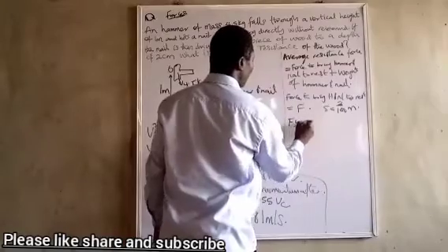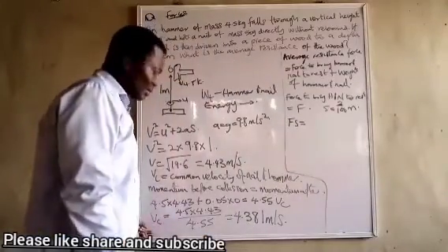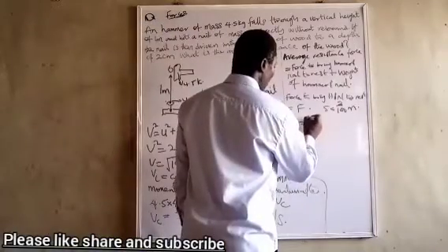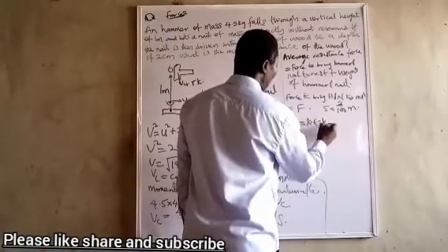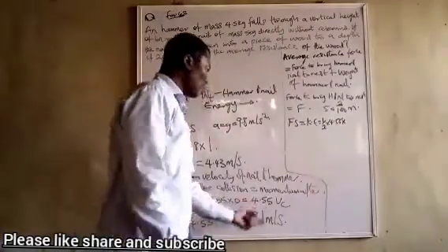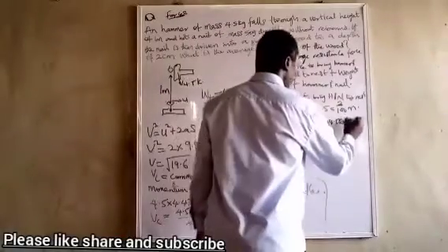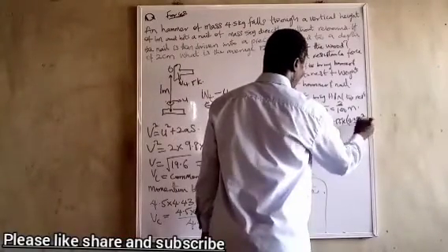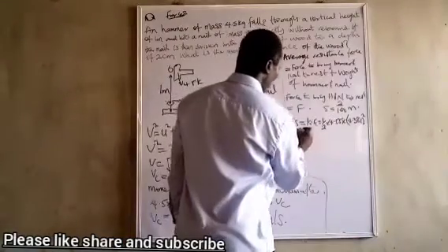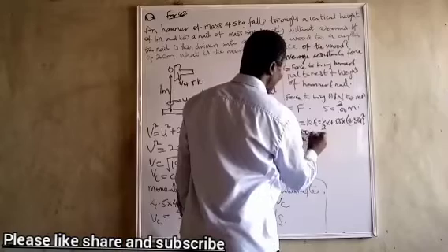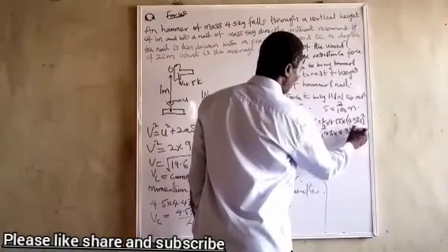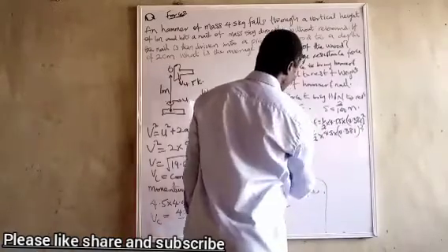So Fs will be equal to the initial common kinetic energy of the nail and the hammer, KE, which is half times 4.55, the common mass, times Vc squared, 4.381 squared. So F is equal to 100 over 2 times half times 4.55 times 4.381 squared. And what does that give us?